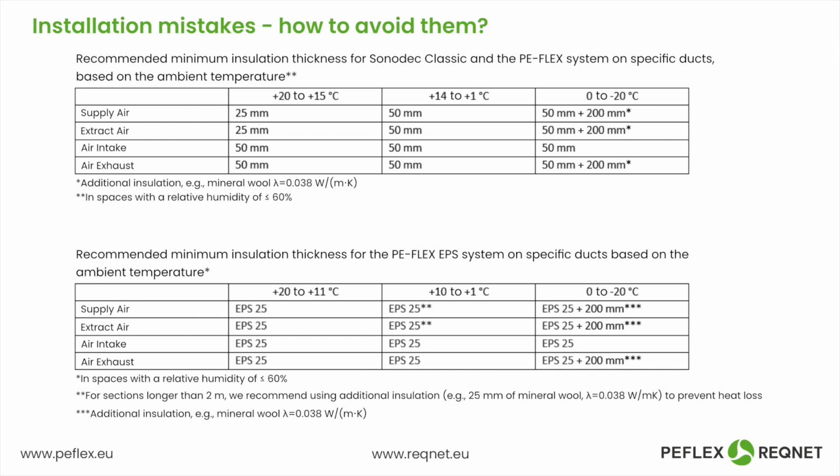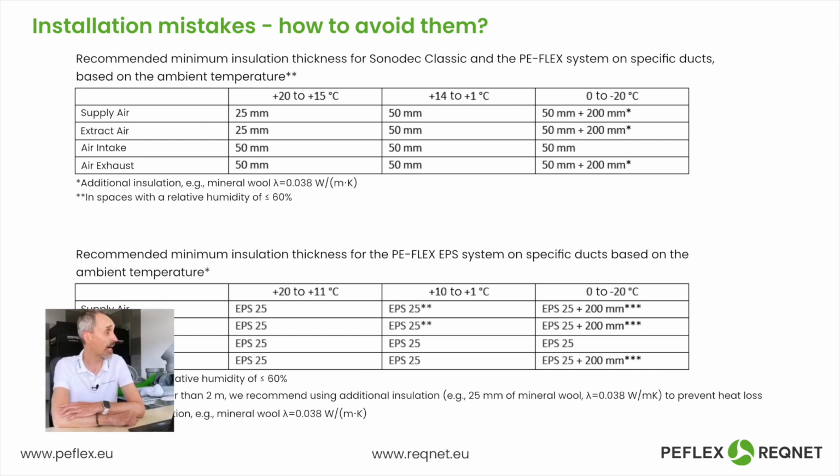To install the supply and exhaust system in this setup, and if we're already moving into the cold zone, needing an uninsulated, unheated attic, then in reality that's the outside temperature, so at least 20 centimeters of wool insulation plus up to 50, right? So in reality, the thickness of the insulation would have to be at least 250, but the optimal solution would be if the insulation thickness was 40 centimeters. So we end up with something like this. A 200 millimeter pipe, 40, that's already a meter.